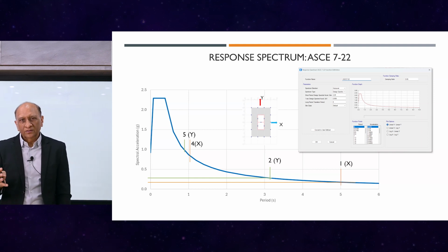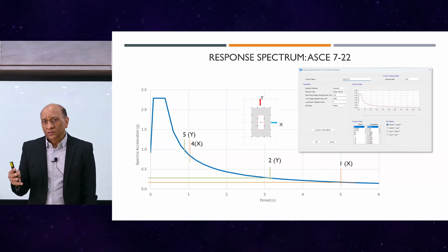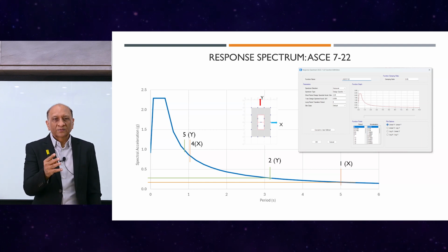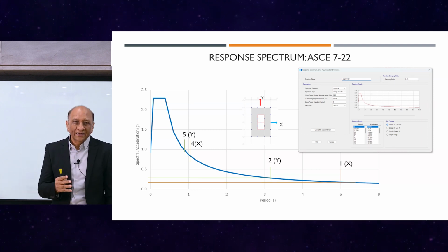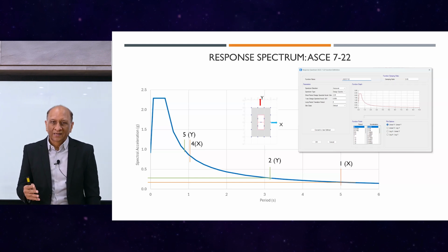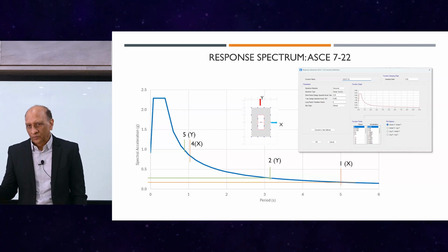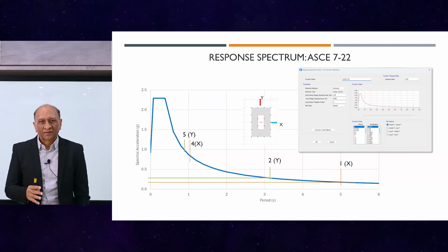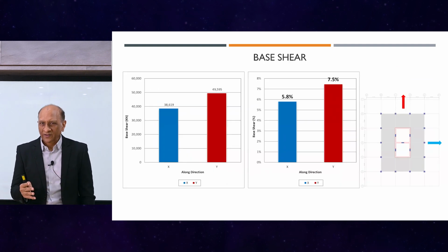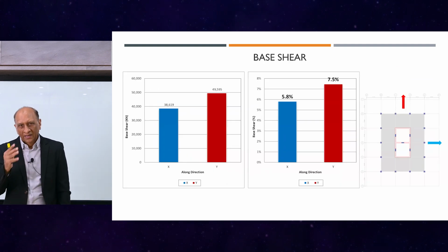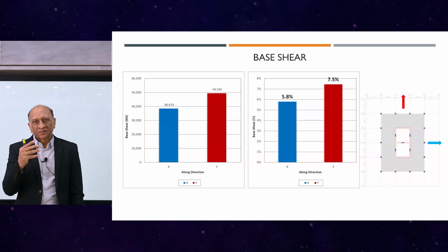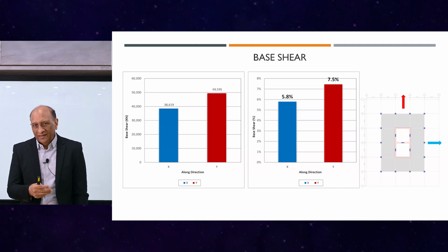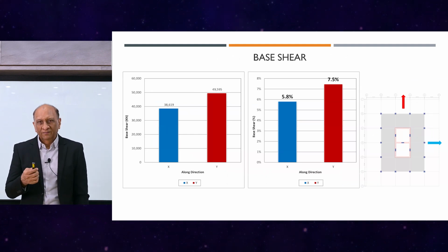As we move towards higher modes, even though their mass participation ratio will be less, maybe 20%, their response coordinate is large, so their contribution will still be large. Even though we have roughly 50% for the first modes and roughly 20% for the second group of modes, their ordinates on the response spectrum are different, so their contribution will still be significant, and we can see that later. This is what's happening in the building response using the gross sections and with the R factor.